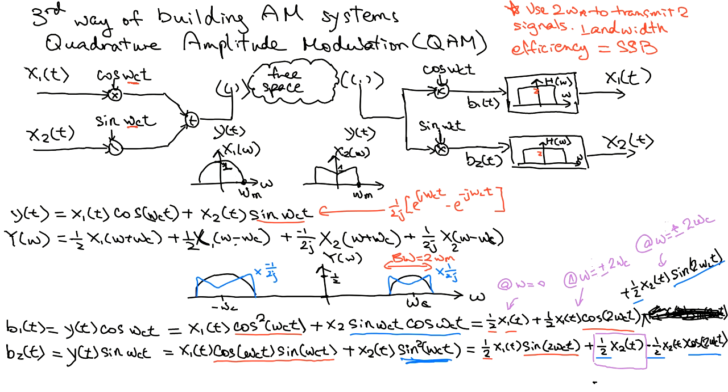which we will talk about after the midterm. Okay, the transmitter and receiver structure is the same. Just that in modern days, x1 and x2 is not analog information anymore. It is high speed digital information. So we will come back to this QAM thing very often when we talk about digital transmission.